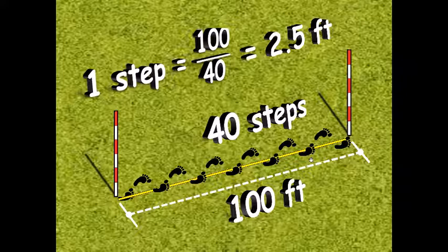That is the distance you cover when you take one step. And then when you know that, you can quickly find out distances by walking on that path, and that gives you a method which you can use when you don't have any other instrument, or when you're not interested in very accurate results, you just want a rough idea.